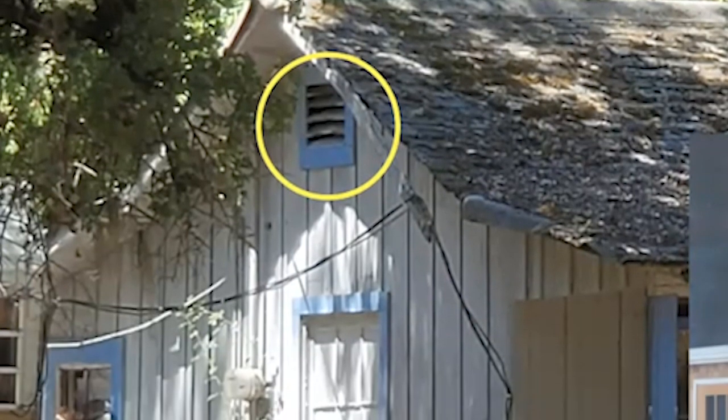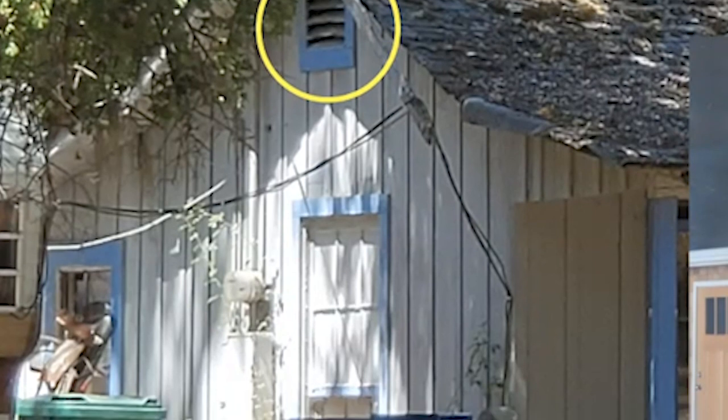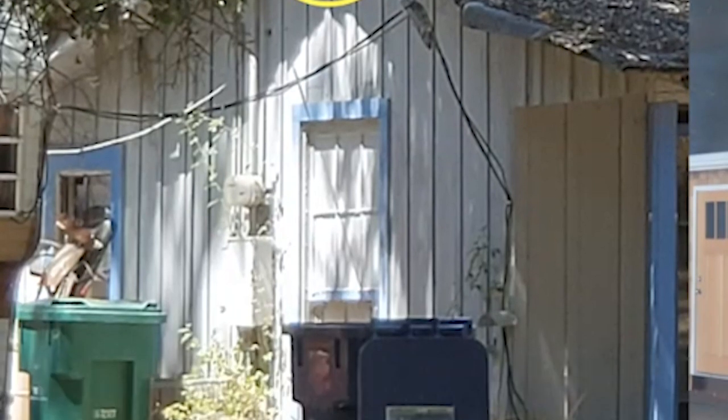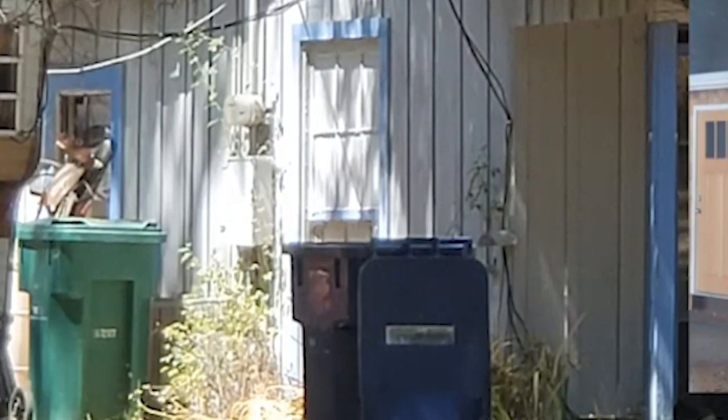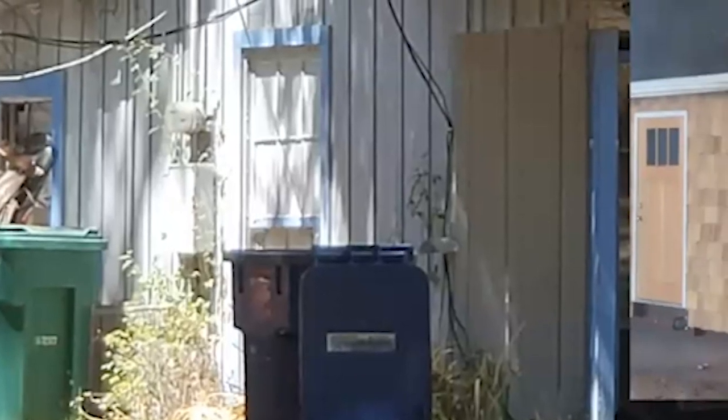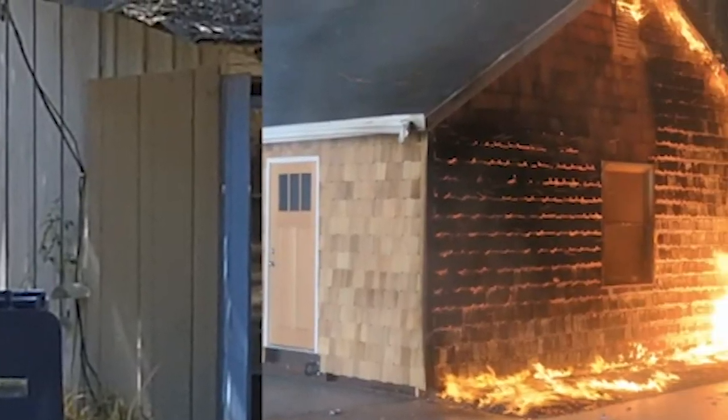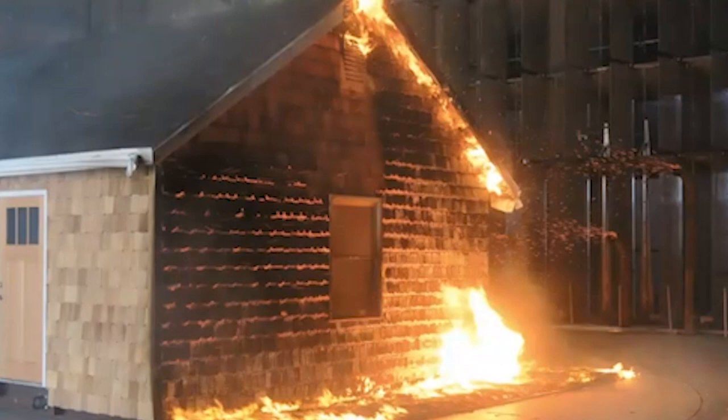And the other thing that is pretty apparent is that should the siding on this home ignite, the flames can burn up the building, impinge, in this case, on the window, but also get to the vent. And in those situations, the vent would also have to be able to resist the entry of flames.